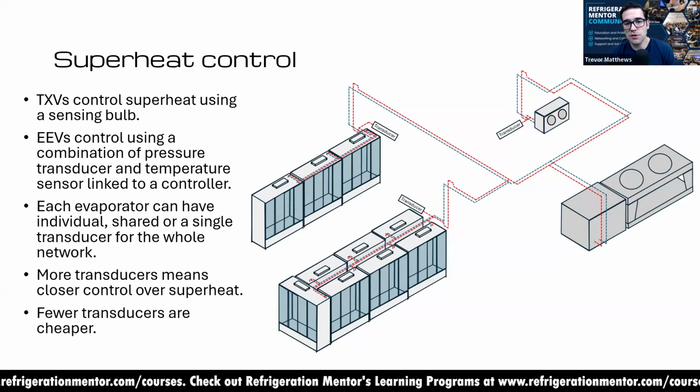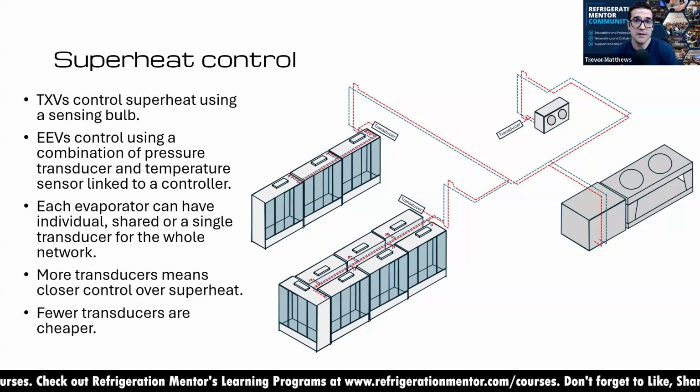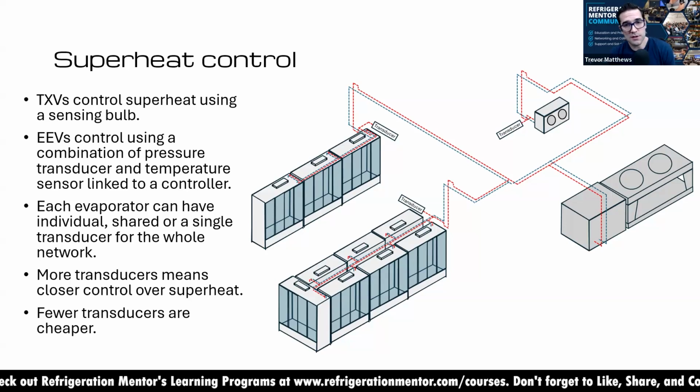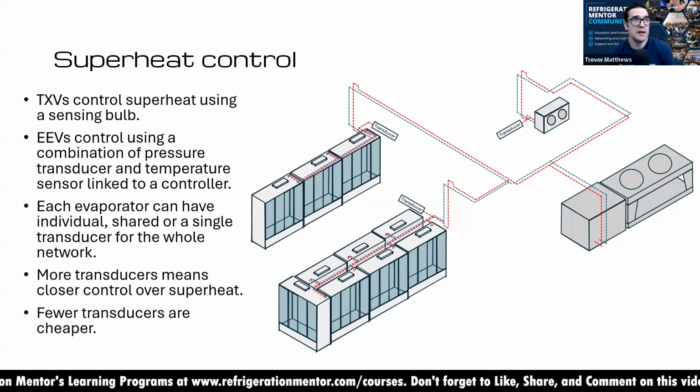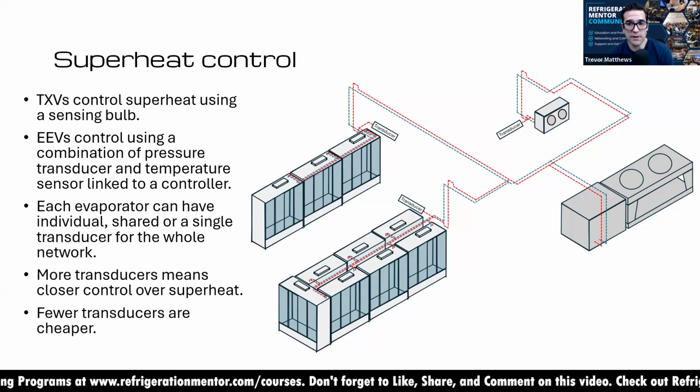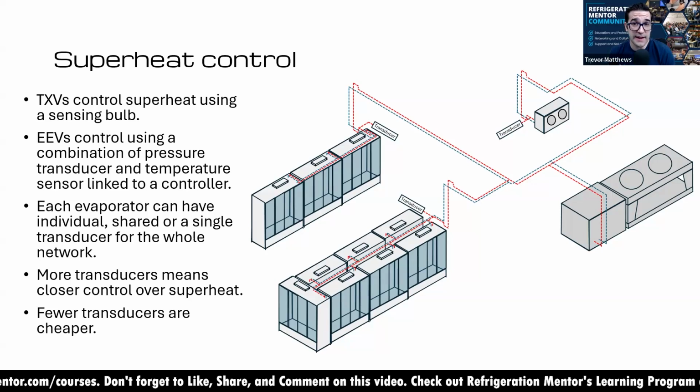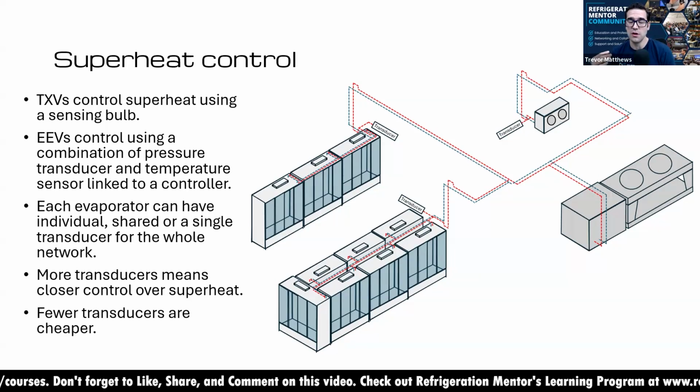But it's with CO2, which I am loving, there are so many more trends that we can get in the control. So you can look at an actual system. You get the superheat, you get the suction temperature, suction pressure, you get the discharge air, the supply air, the defrost termination. And this stuff, it's not new to the industry. We had this 15, 20 years ago. It's just that it's more apparent now because more people want control, they want visibility. And for me as a technician, it helps me troubleshoot cases so much faster.